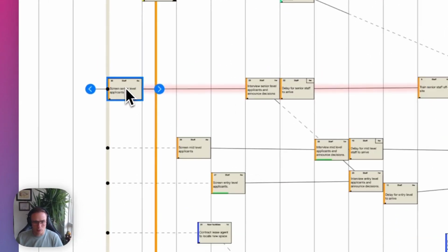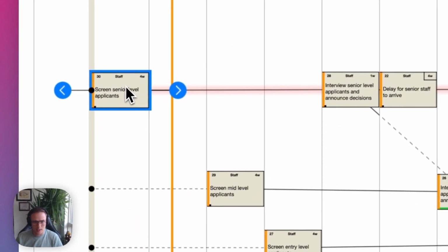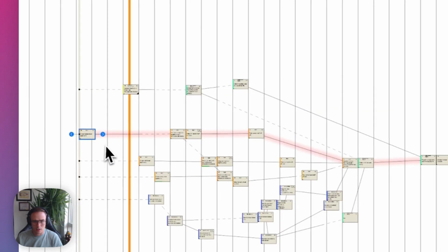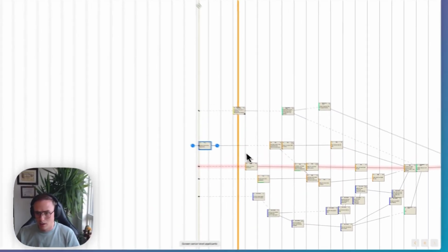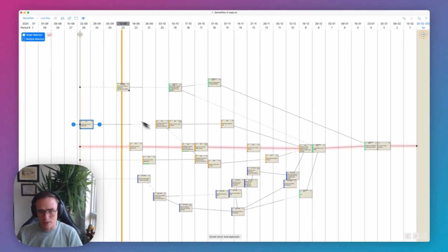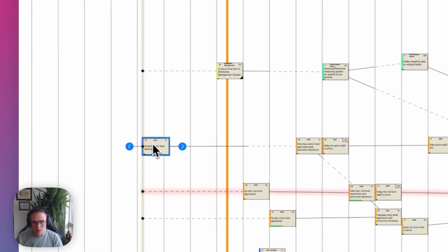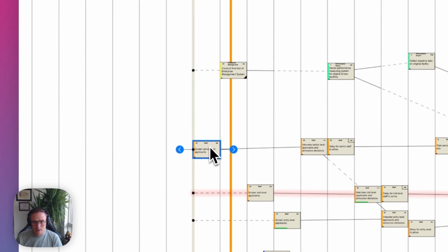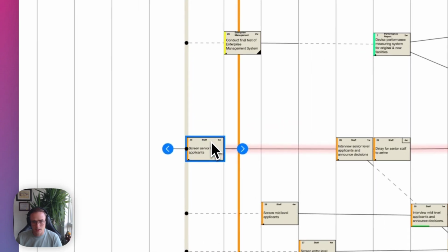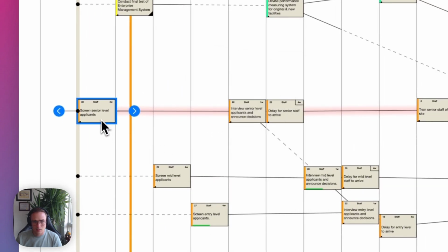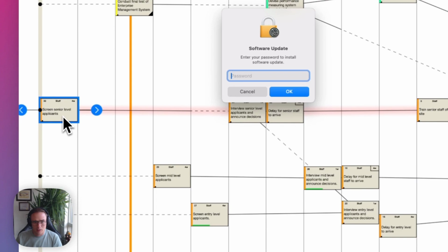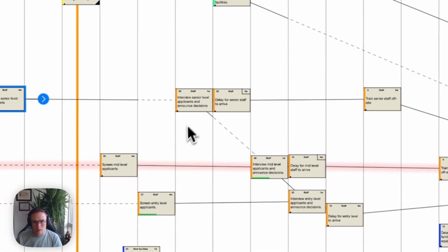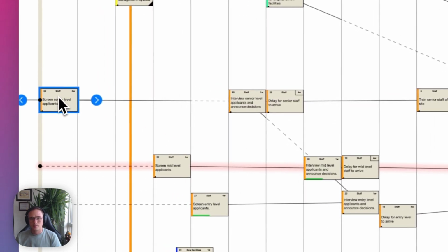If I were to grab, let's say, this task, and maybe I'm changing the float in it, you can see that my critical path changed, right? So moving back to the original space, here's my critical path. If I were to start this task earlier, now my critical path changes.